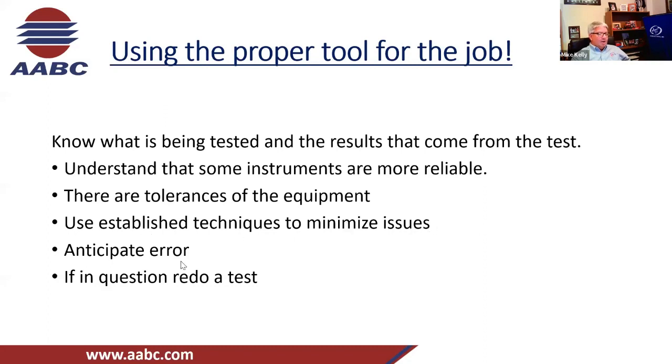And anticipating error, meaning you look at things, and this sounds like a purveyor of doom or a negative way of looking at things, but you got to look at things to say, this traverse isn't going to be good. It's coming off of that elbow, and this is the best we can have. Or, testing these airflows on all of this equipment, and we're going to have stratification here. We got to be wary of it. You have to anticipate it to know, hey, this testing is skewed because we had this anticipated error, and sure enough, it shows in some of our readings.